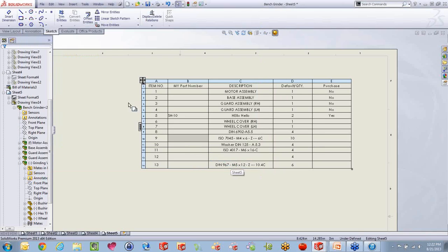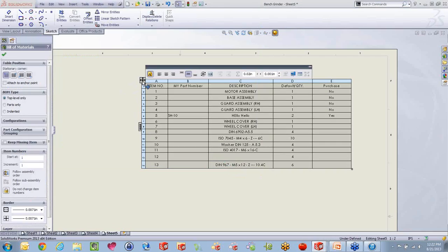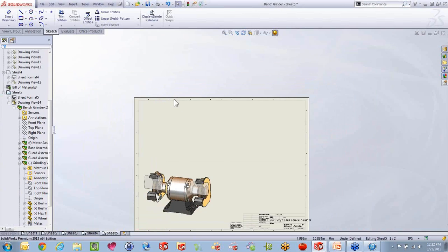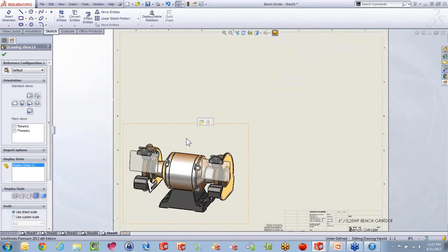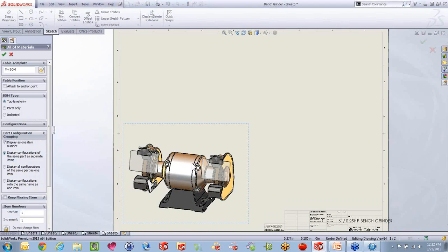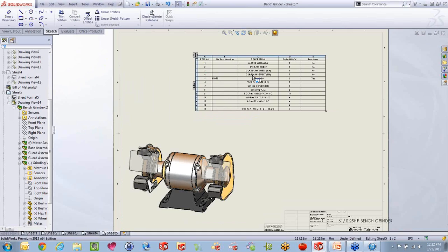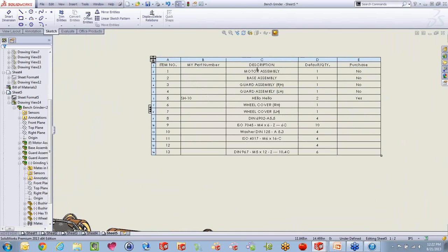What you will see now is that when I go in here and I delete this BOM, you see this is our customized one that I just created. When I delete it and I go to insert a new one, this time I'm going to go to the S key. I've actually placed my bill of material right on the S key. You will see that it sees that as my template. And when I place it, look at that. It remembered all those different places.